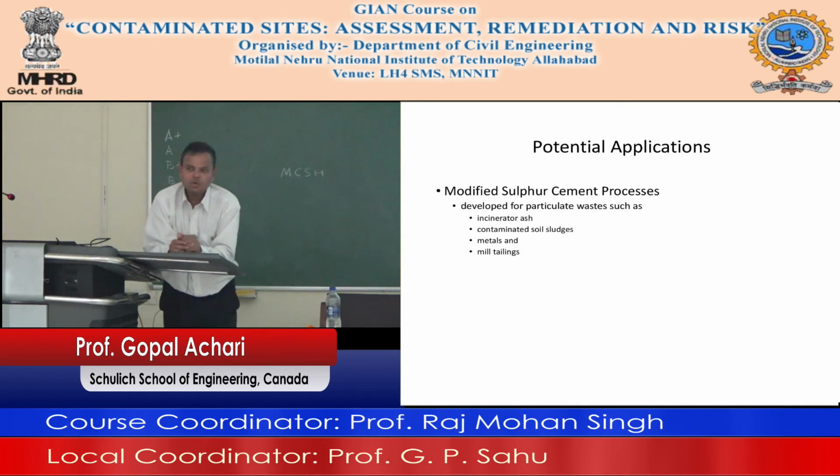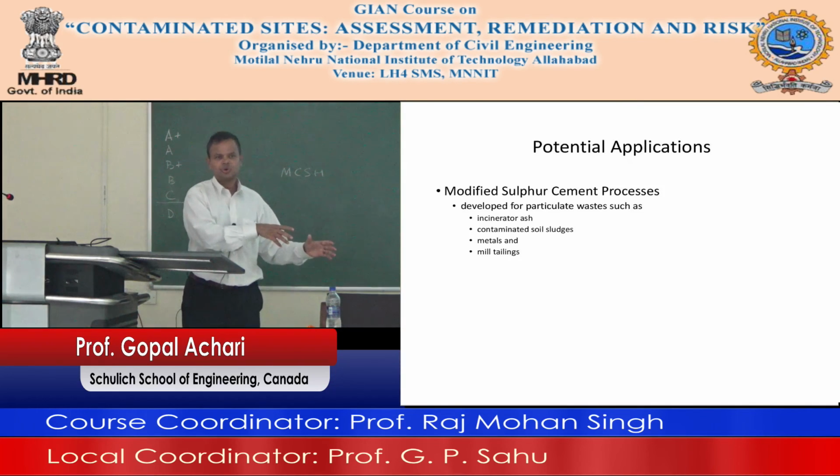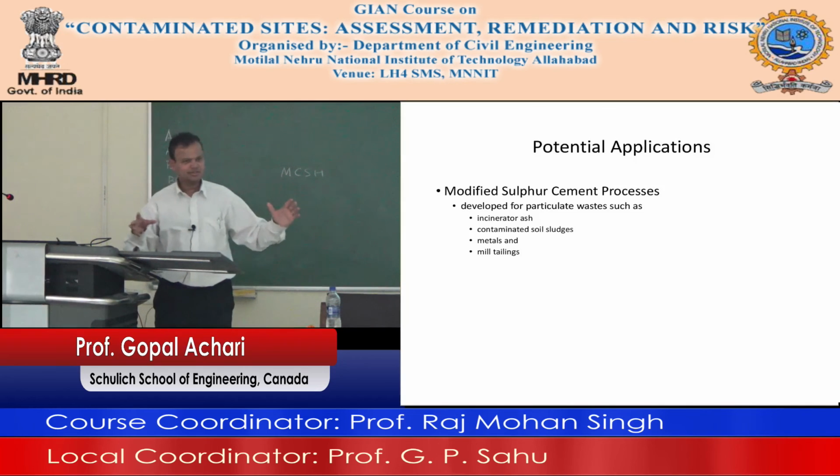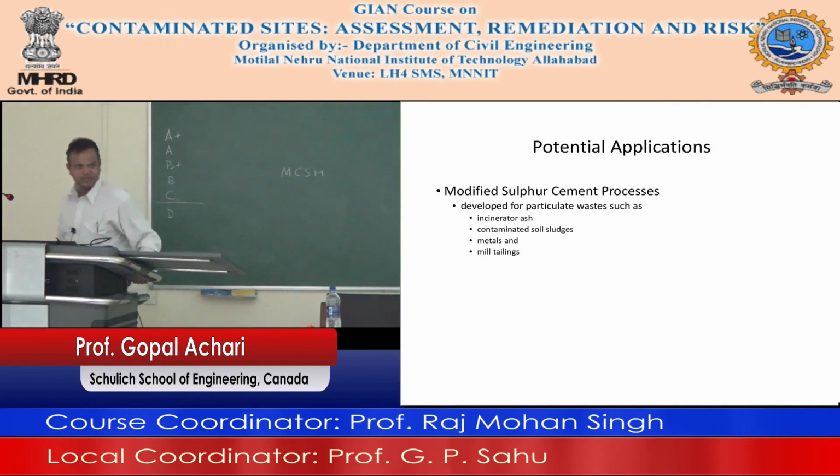Fly ash may have a little bit of lead because of the source of coal, but by and large it's not bad. But incinerator ash depends on what you incinerate, so it can have chromium, cadmium, whatever went into the incinerator. You will need to do something about that ash. It's not like fly ash, which they put in as a backfill material and so on. You have to deal with incinerator ash and heavy metals.